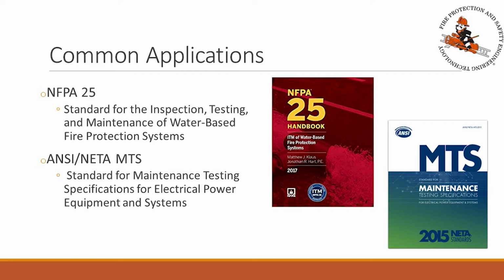The primary one that we've touched on a lot is NFPA 25, which is your standard for inspection, testing, and maintenance of water-based fire protection systems. So this tells you all the different things that you need to do, whether it's a sprinkler system, maybe it's your fire pump system, and all the different things that you need to do, from inspections on those systems to the actual testing, whether that's flow testing or testing the different systems hydrostatically. Those are all the different things that NFPA 25 provides. It also provides, again, the frequency at which these need to happen.